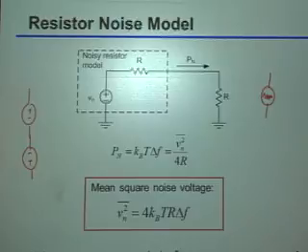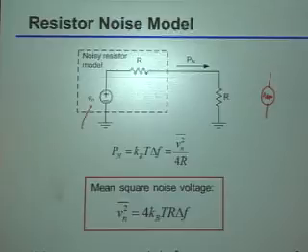Okay? So if we now want to figure out what the actual quote-unquote value I should plug into this, and by the way, when I say the value here, what I really again mean is I want to know how much variance can be coming from that voltage source. Okay? So if I want to figure that out, what I can actually do is use this power property that I mentioned earlier. Right? I already said before that the power I can extract due to that thermal noise is just kB times T times the bandwidth. Okay?